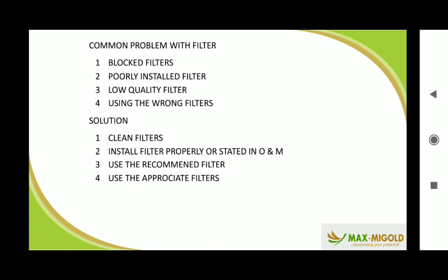Then solution: clean filter. How do you clean filter? You use pressure wash. After you remove it from your AC, use water to wash it, pressure wash, then dry it in the sun.